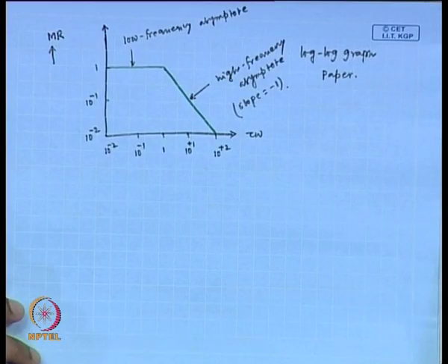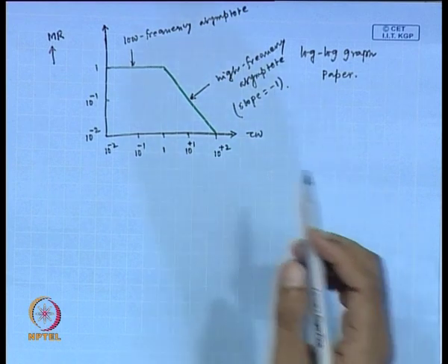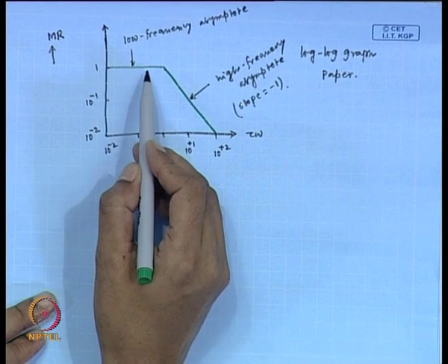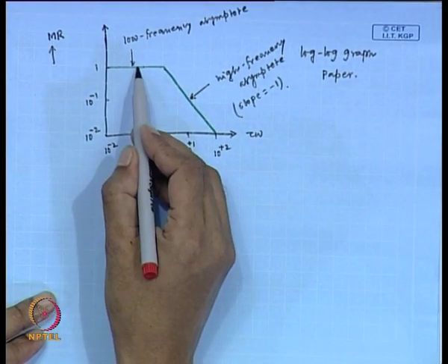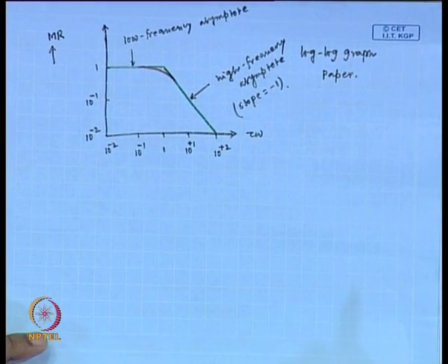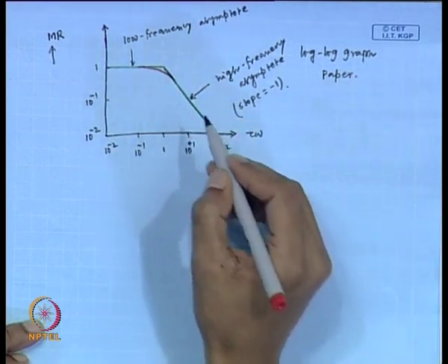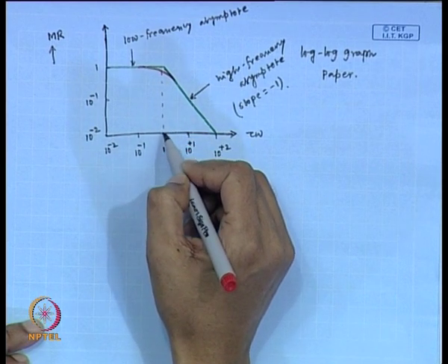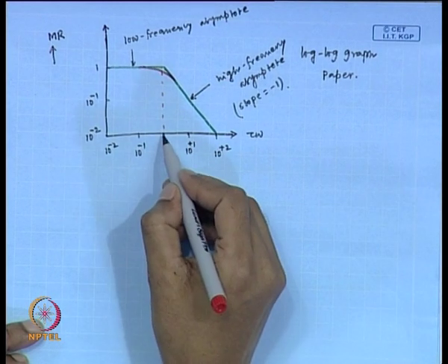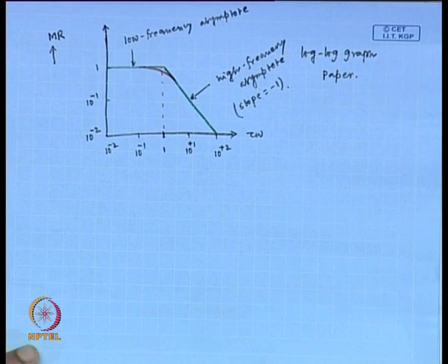Accordingly, we need to construct the Bode diagrams. I mean, this magnitude ratio versus tau omega plot should look like this. And the corresponding tau omega is 1 here. This is the corresponding natural frequency in this first plot. So, this is the asymptotic consideration in terms of amplitude ratio, and we obtained this plot. Similarly, we need to consider the asymptotic consideration in terms of phase angle.